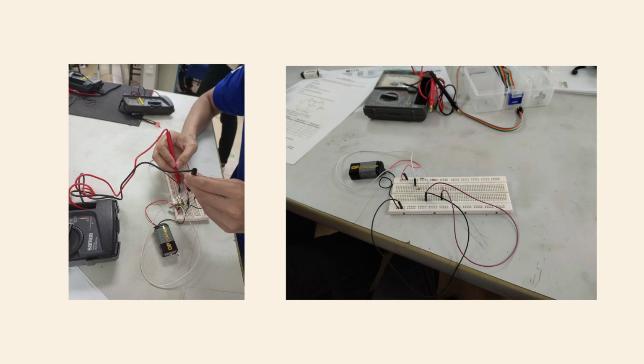And on the right side is how our circuit looks like in the solderless board with battery as a power source. For part A, we find that analog multimeter is more accurate or closer to the manual calculation value, while digital multimeter is heavily impacted from the battery as it needs its own power to operate. So when the battery is low, it will eventually affect the reading value. And for part B, turning the knob of the potentiometer will change the resistance value of the potentiometer, and the bridge is balanced when there is no current or voltage across the meter at the middle of the Wheatstone bridge.